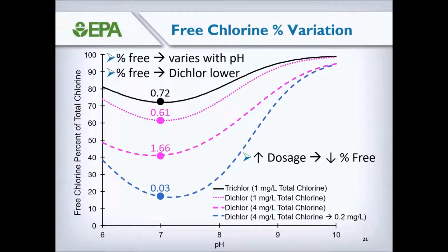And then finally, the thing we have to deal with in real water is that we actually have chlorine demand. So we have to take that into consideration. The cyanurate that's in the water can be considered essentially conservative, and it's not going to go away over time, but the chlorine in the water can react away, and your total chlorine concentration can go down, while your total cyanurate concentration remains constant, and that's what I'm highlighting here in this last plot.